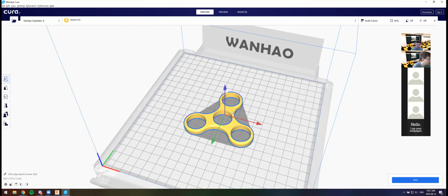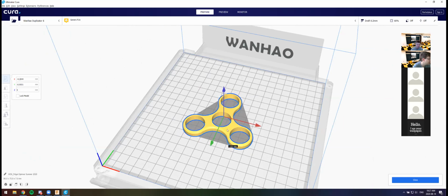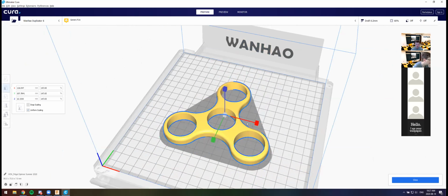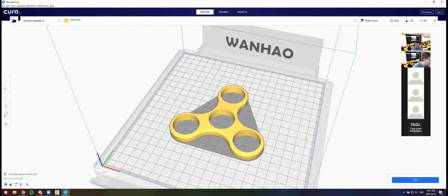Basically, let's just talk about movement again. So, movement. If you click the next one here, it's called scale. Scale is something you can do to an object if it's not an exact size that you want. So for instance, I can make it bigger, make it smaller, right? In our case, we know that we have 22 millimeter bearings that want to fit in these holes.